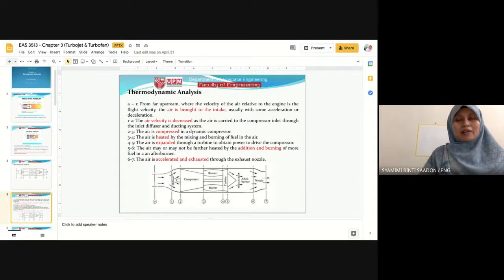That is for a gas turbine power plant in industry, at the factory. But for a jet engine, it is the same cycle, still a Brayton cycle, but an open system, an open cycle. So what do we mean by open? I will explain the general cycle. We first have compression, then combustion, and then expansion, and then the air is rejected to the ambient. There is no condensation.